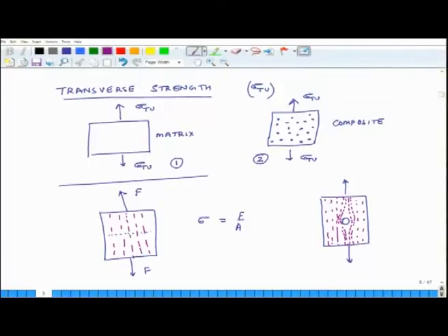So, the stress lines get concentrated in this area of concentration of stress. Same thing is happening in this zone also. Okay. So, what that means is that in the region, let us say far away, suppose in this region stress is still F over A, but in this area of concentration stress is more than F over A in the area of stress concentration.